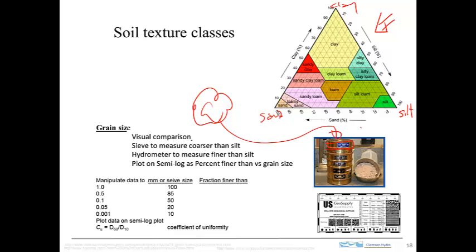And if you were to do that, for example, and you had a little bit of silt and clay, say 80% sand and 20% remaining split between silt and clay, then it would work like this. So the sand fraction is given by these numbers, and so 80% sand would be right there, and then if it's equal fractions of silt and clay, then it would be halfway along between these two boundaries.